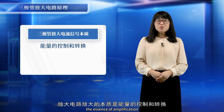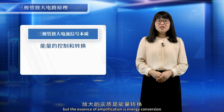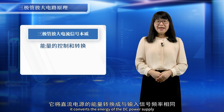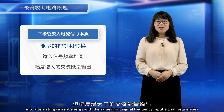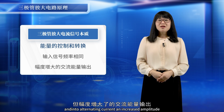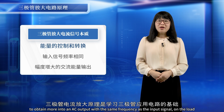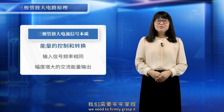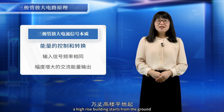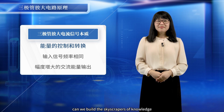The essence of amplification is energy control and conversion. On the surface, it increases the amplitude of the signal, but the essence of amplification is energy conversion. It converts the energy of the DC power supply into alternating current energy with increased amplitude, obtaining an AC output on the load with the same frequency as the input signal. This is the basis for learning the application circuits of the transistor. We need to firmly grasp it. A high-rise building starts from the ground. Only by laying a solid foundation can we build the skyscrapers of knowledge.